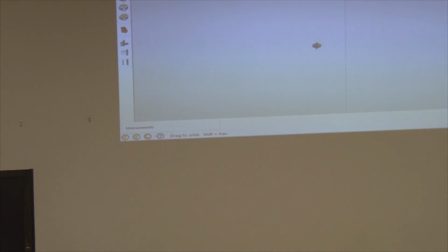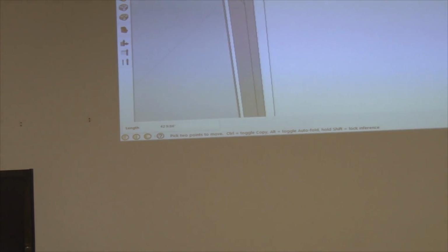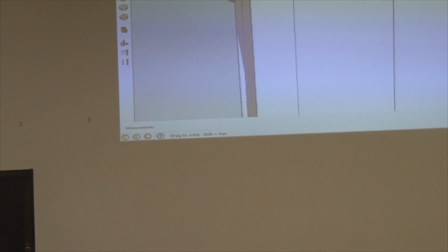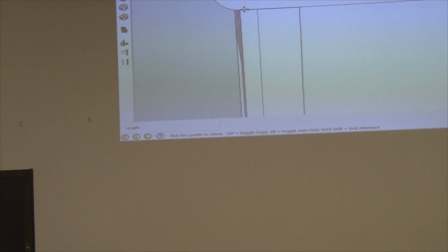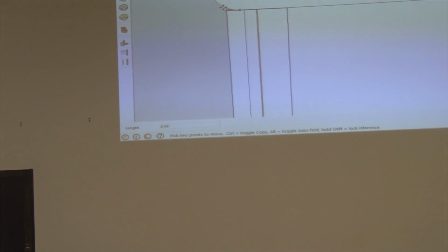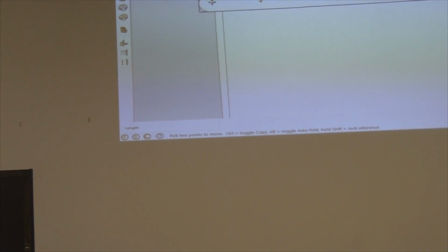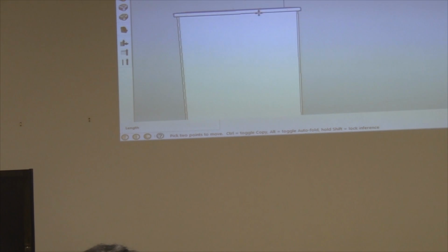And I'm going to orient myself and bring this to the back. I'm going to stick it right there, but I've dropped it there and I'm going to move it 1/8 of an inch out, because I know that it has a 1/2 inch overall reveal on the top. This is a 3/8 inch radius bull nose, so 3/8 plus 1/8 is my 1/2 inch overhang.